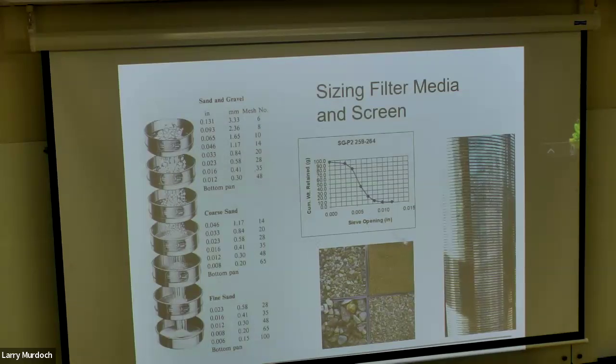Okay, so when the well is completed, you need to select a size of sand that filters out the particles in the formation, and is also prevented from entering the well by the well screen. There's a variety of different grain sizes of materials that are available for well completions, and you would select that based on the size distribution of the particles in the formation.